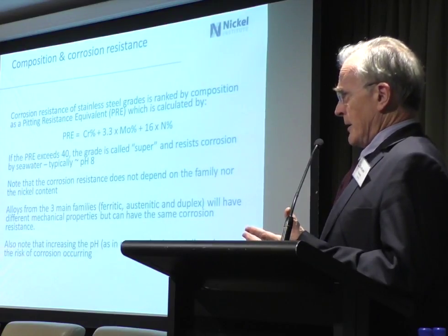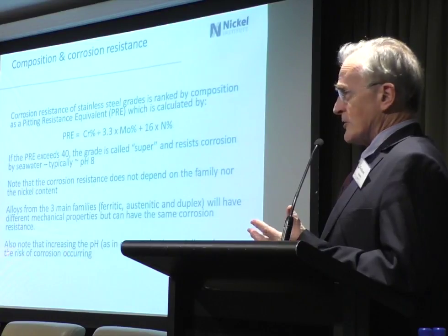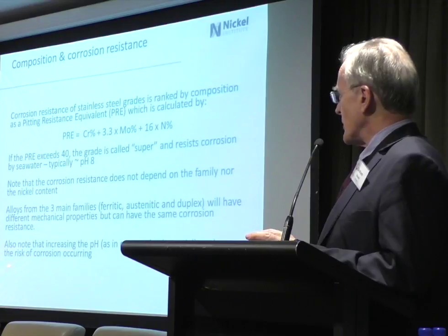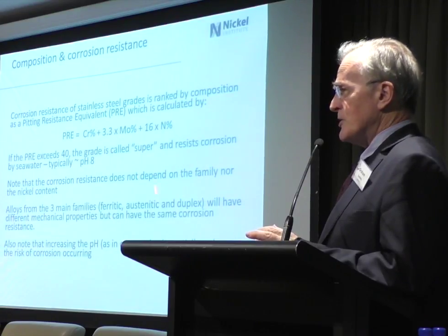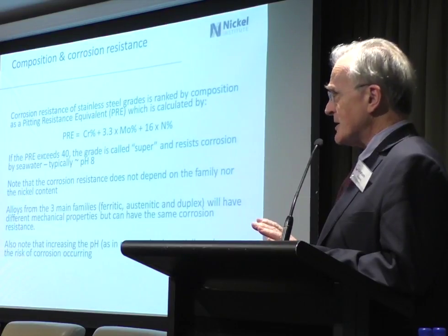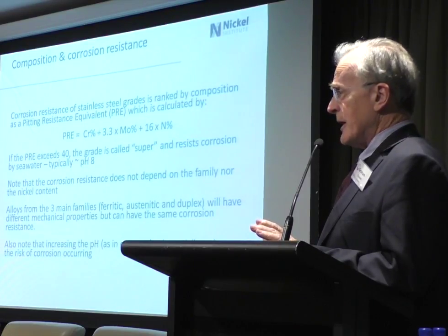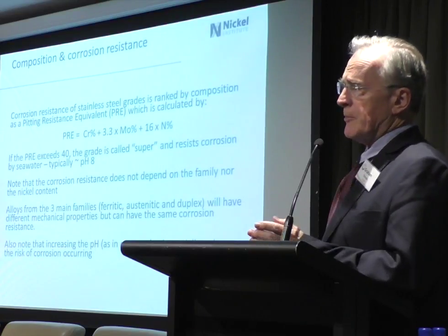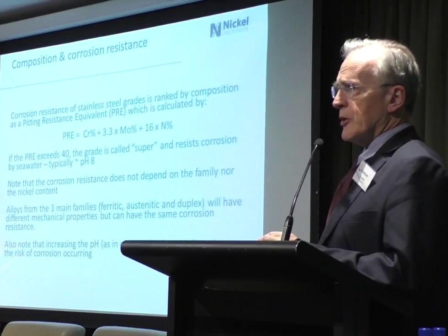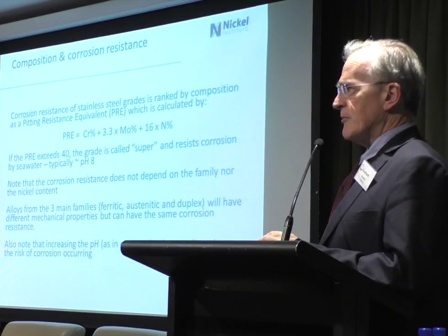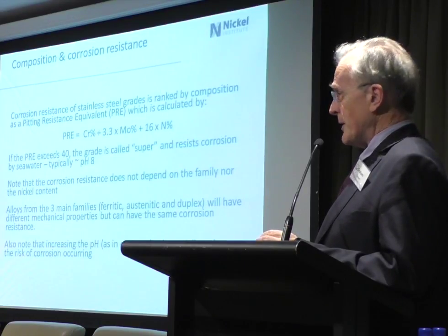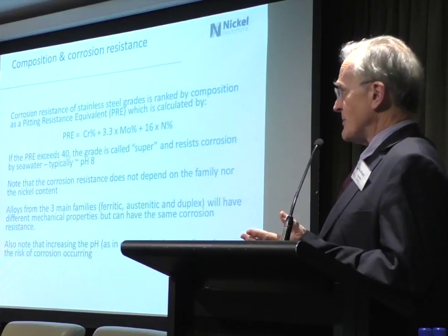And I'll tell you now to note that if you put the pH up, then you will substantially reduce the risk of corrosion occurring for stainless steels. Exactly the same way as with carbon steels, and it's borne out by, you go look up corrosion tables, mixtures of sodium hydroxide, sodium chloride, and suddenly you find that stainless steel is just about invulnerable when you get way up in pH. Much the same as carbon steel would be.